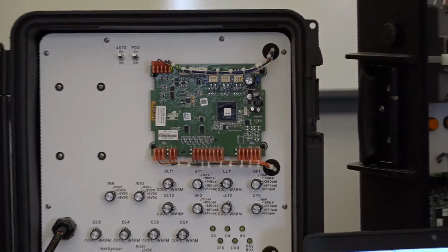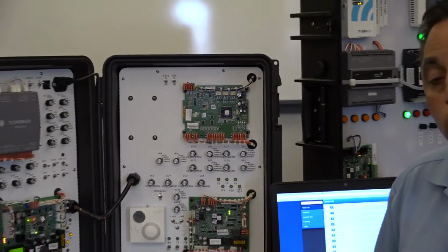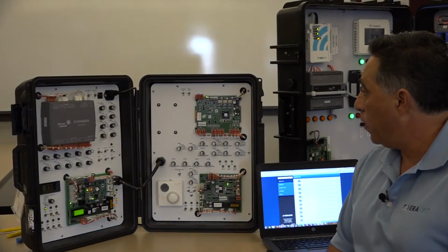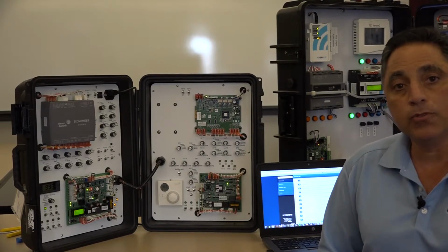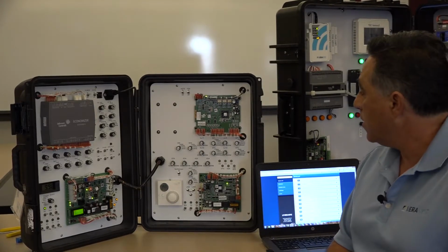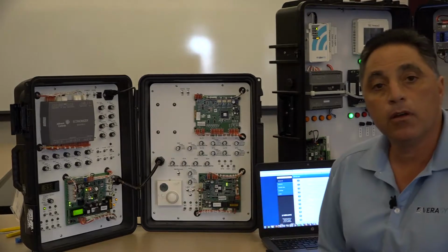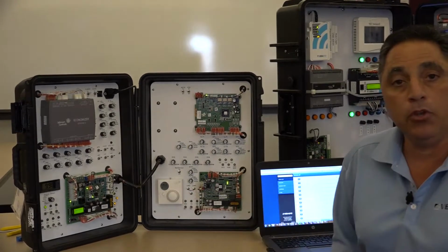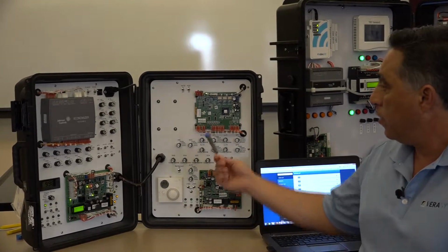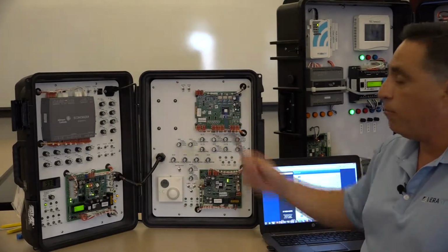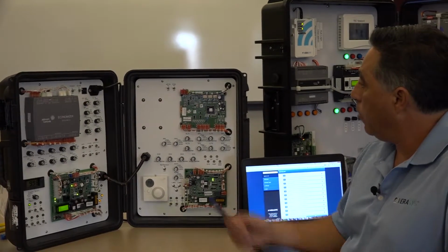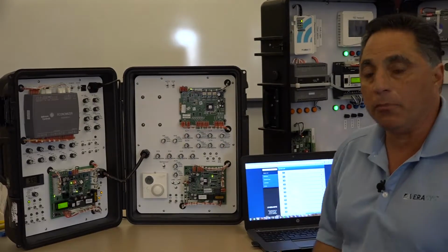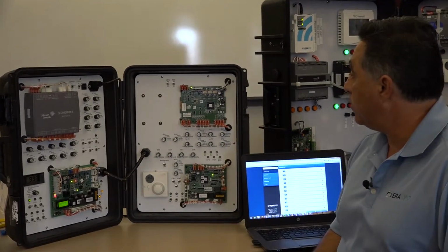You have one controller for every two circuits of this system. So let's say I have a 4-circuit rooftop with 4 compressors, then I would have to have two of these FDD boards, and they will be communicating on the same bus. Within this example right here, I have one. And the important thing to know about this is that from a factory perspective, you will have all this factory mounted, or you would have to do this in a field retrofit.